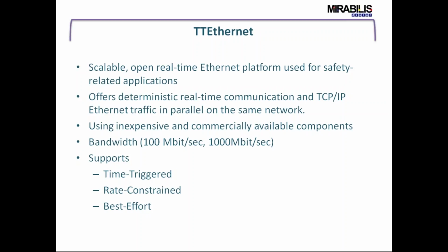One of the main reasons for selecting TTEthernet is that it offers deterministic real-time communication and also the ability to transmit best effort and rate-constrained traffic along with time-triggered traffic in the same network itself. It also requires low hardware cost, it is well established with open world standards, and it is a highly scalable technology as well.